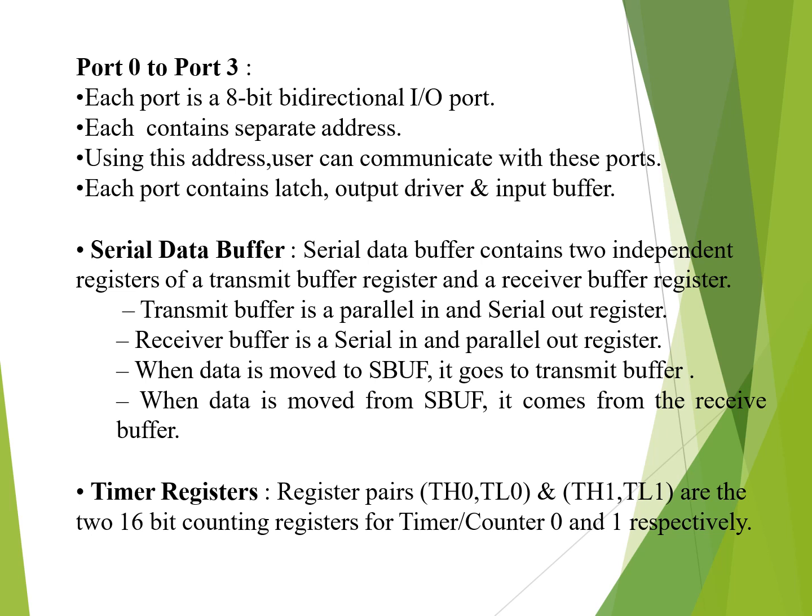8051 is having two 16-bit timers, named timer 0 and timer 1. Both of these timer registers can be used as two separate 8-bit registers. Timer 0 can be separated and used as two 8-bit registers, TL0 as well as TH0: timer lower corresponding to timer 0, timer higher corresponding to timer 0. The same way, timer 1 can be used as two 8-bit timers, TL1 and TH1. That is timer lower for timer 1, timer higher for timer 1.